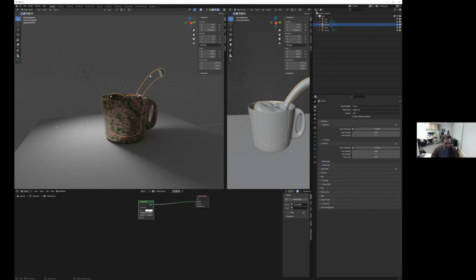I would really stress trying to do the simulation again and again with different variations and different objects in the way, and then possibly adding a fire, because you still need the domain and you need the inflow, but those are pretty much the bases, and then you can expand on that. So instead of liquid, you just choose gas or fire, and then going through the time series, replaying or baking, it's the same idea.